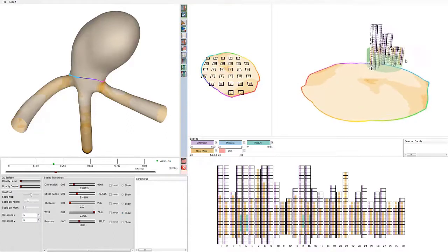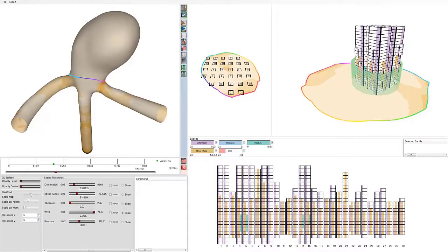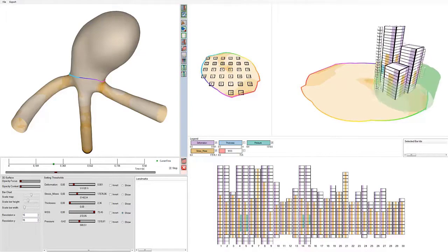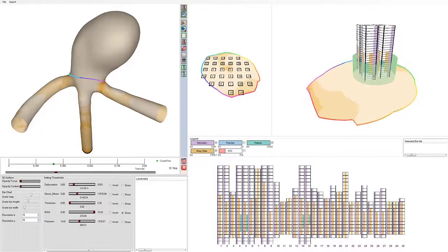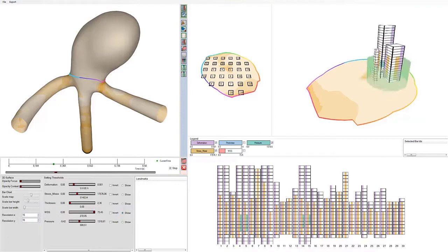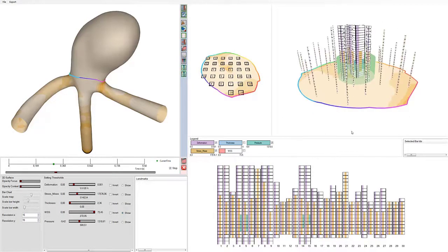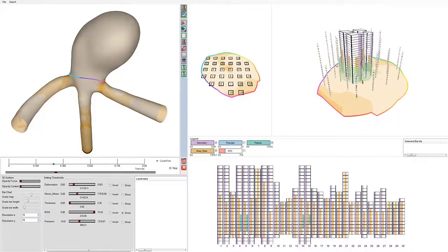The next option to avoid occlusion is to set a focus region in the shape of a cylinder. The user can activate the cylinder, translate it, and change its radius. Bars outside the cylinder are visualized in two selectable ways. The first option is that the bars outside the cylinder disappear completely, where the radius of the bars within the cylinder is adapted depending on the distance to its center. Bars close to the cylinder midpoint become wider. The second option is that also the bars outside change their size depending on the distance to the cylinder.